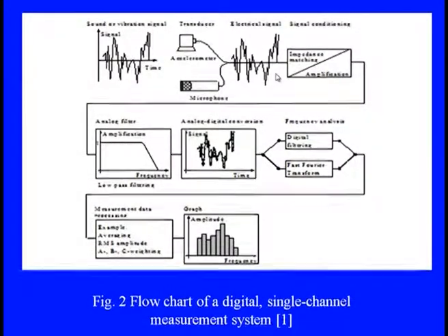We can see that wherever the positions are, we can put the microphones or the accelerometer. These are my main transducers, and through them I can get these signals. Or even, when we have such things with digital filtering, we can get the frequency peaks, the FFT. So, this is my time domain, this is my frequency domain, and it can clearly give what kind of exciting frequencies there are.